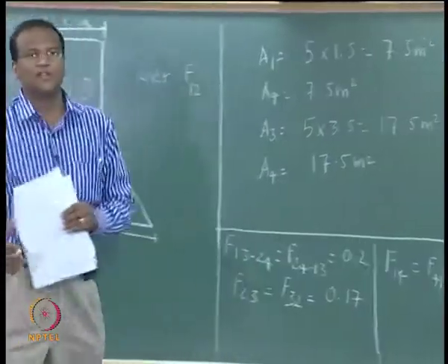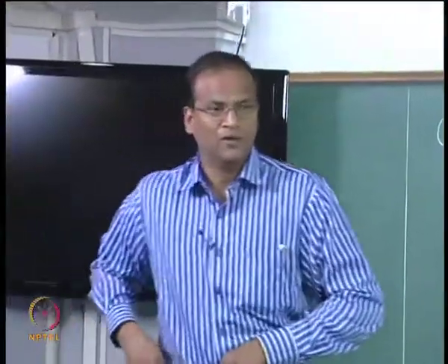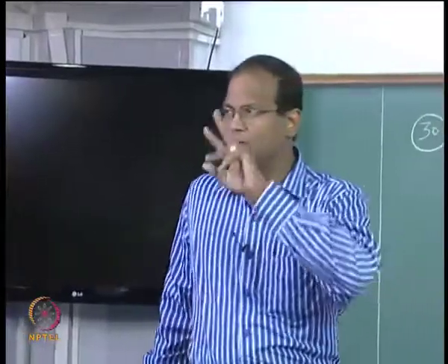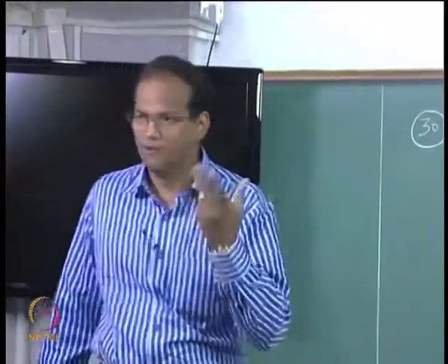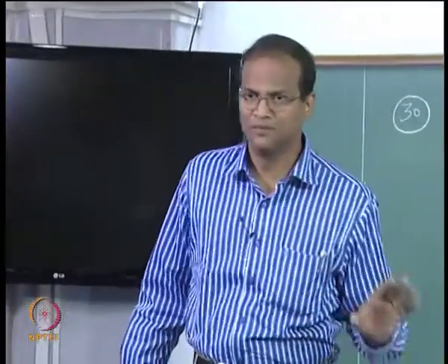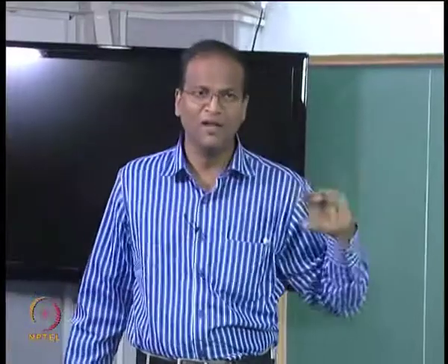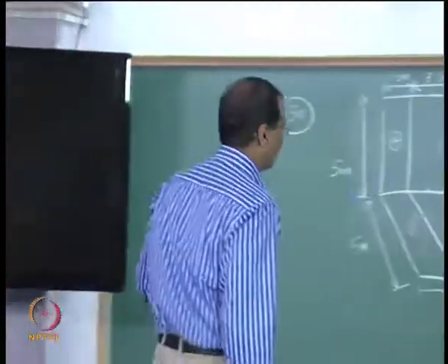now the manipulation will start. You have to apply the reciprocal rule and the decomposition rule. So it is just the manipulation of reciprocal rule and decomposition rule, nothing else. Summation rule will not work because it is not an enclosure. So this reciprocal and decomposition rule repeatedly you have to apply, use your common sense, and then we will have to crack the problem.